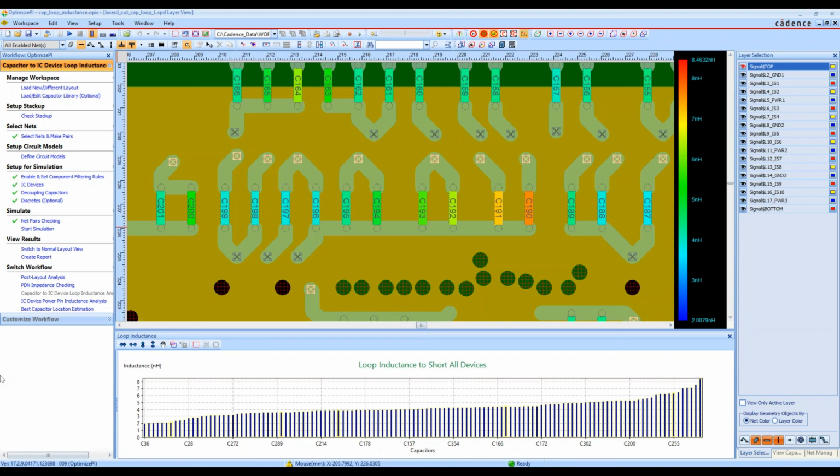So that sharp point makes it tougher to get around, and the current density there becomes higher, which can become more problematic right at that point. If you round that or put an edge on it, then the current density doesn't get as high because it doesn't get channeled into one place quite as badly, so it works a little better.